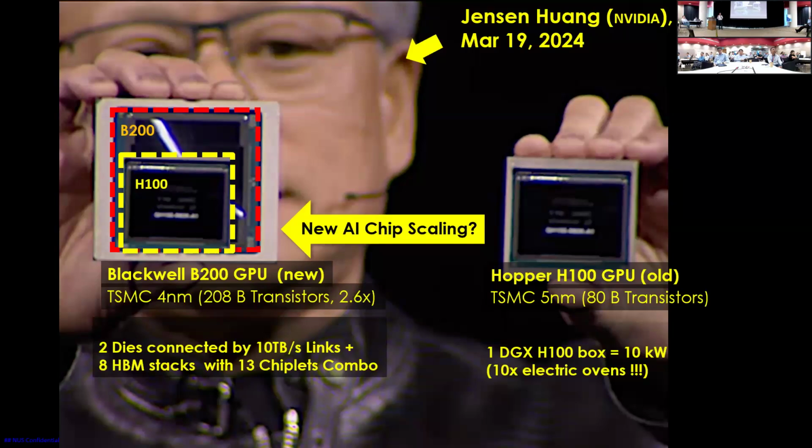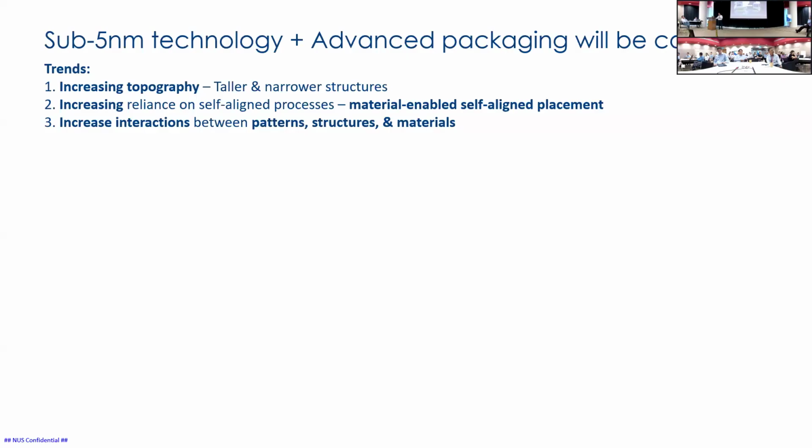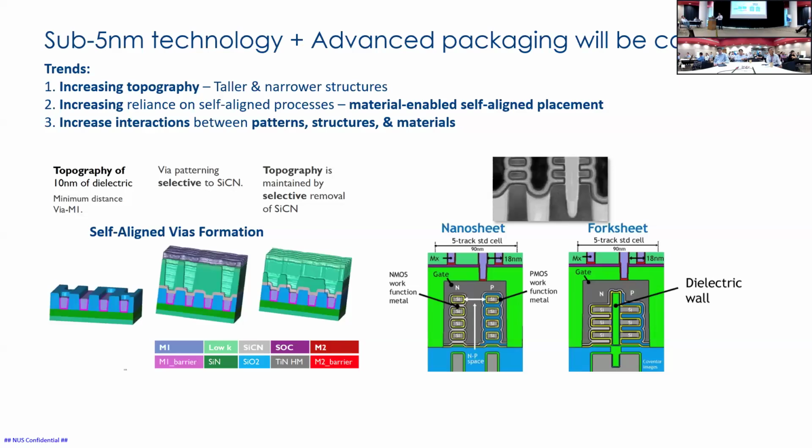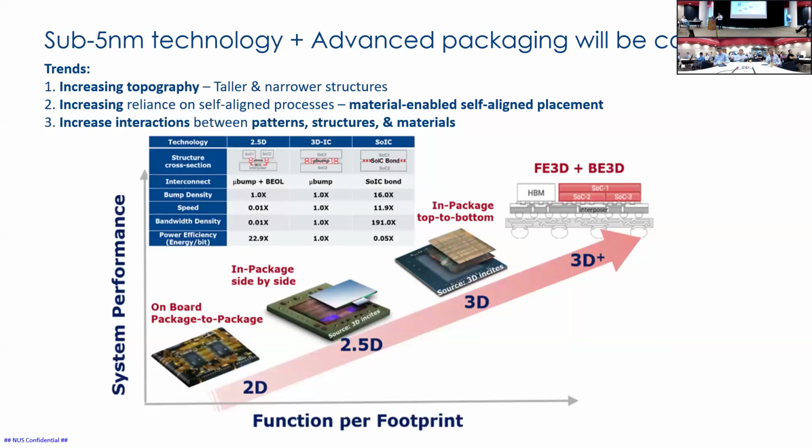And so now there's a major motivation to do defect detection in stacked chips because I think it was mentioned before by a previous speaker that it is actually very difficult to isolate defects in these chips, especially if you need to do it in real time and online. The reason is that you want to detect the soft error faults while it's running, and then correlate it back. That's what I think currently we are doing. And on top of that, the technology node that we're talking about, sub-5 nanometer, is highly complex.